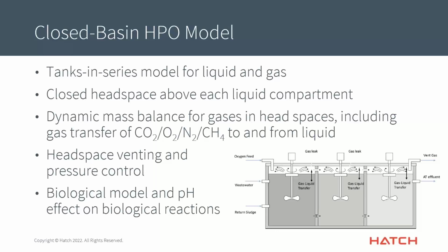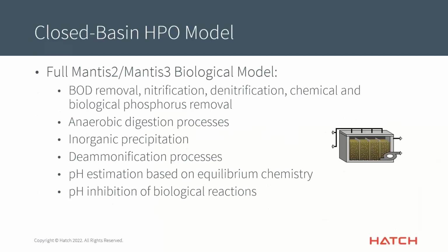Then you have that connecting part, which is the mass transfer model that allows those gases to be exchanged with the liquid. That will be done for oxygen, obviously, but also for all of the gases, including the release of carbon dioxide back into the headspace and so on. So those are all there. And then we have some sort of control system that allows us to control how the gas gets out at the end. And then we, of course, have all of our biological reactions going on in the system. The pH does have an effect on those, pH being an important aspect in HPO systems, because you're holding back a lot of carbon dioxide and potentially driving that pH down.